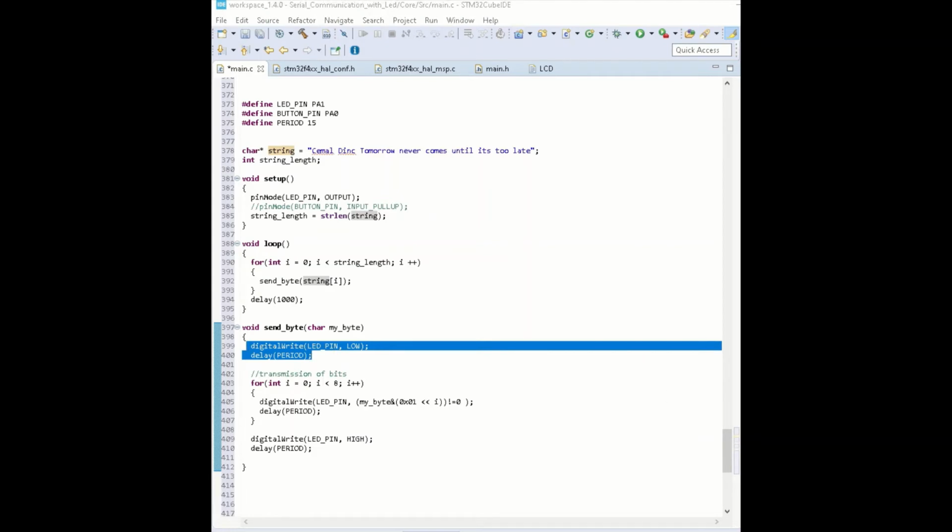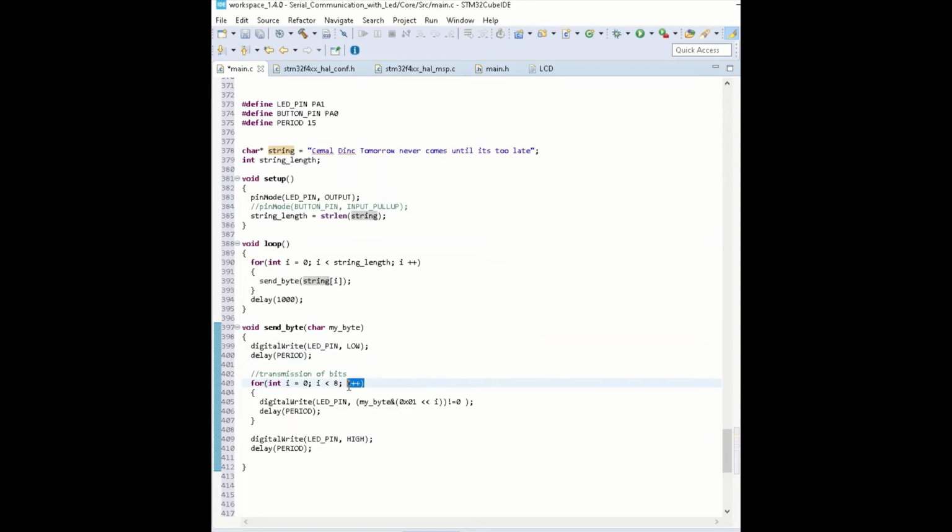The for loop is for the bitwise operation. The first thing we do is get our byte. So here we are using a for loop to do this 8 times. Here we see we send the data bit by bit, and then we shift by one bit, so we produce our mask so that it will be 0x01. Then we check if our bit is 0 or 1.